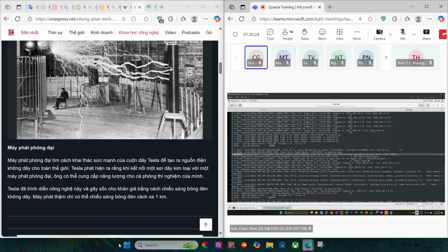Okay, we can see on line 108, the first error is QPA UPF illegal state reached. So it's complaining about this, and let's see what further information we can get from here. The time is 20 nanoseconds and the supply set is PD2 primary. So this PD2 primary reached an illegal power state and then we get an error. Next, it gives us the file and also the line number. Let's open up this file. Line number 5, and we remember PD2 primary reached illegal state.